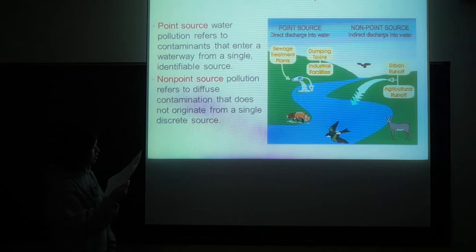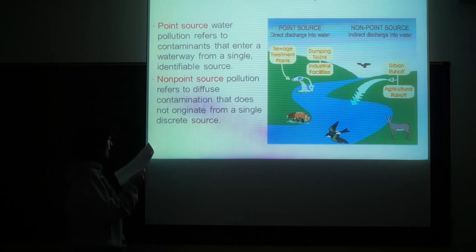There are two sorts of sources, point and non-point sources. The first one, point sources, discharge pollutants at specific locations through pipelines or sewers into the surface water. And the non-point sources are sources that cannot be traced to a single site of discharge. Examples of the point sources are factories, sewage treatment plants, and oil wells. And examples for the non-point source are things like acid deposition from the air, traffic, pollutants that are spread through rivers, and pollutants that enter the water through groundwater.